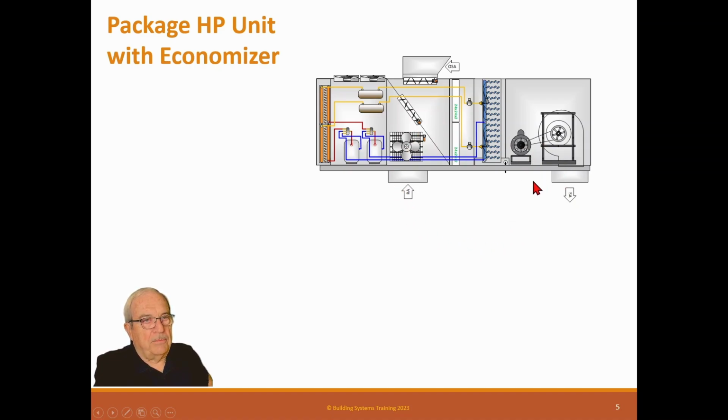When we go to economizer, this damper closes. The air comes in here, goes through here, and comes back. Well, if we didn't have this fan here, then this fan has to pressurize the space enough to push the air out this damper. Now, when we're in regular mode, this return was under negative pressure. It's seeing the suction of this fan. But the minute we close this damper to an economizer, this suction pressure is all used to draw this air in. So there's none here.